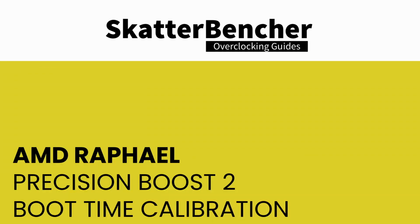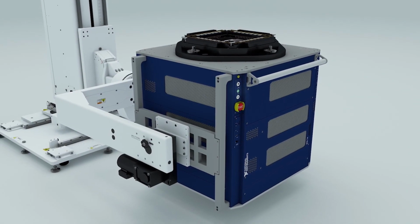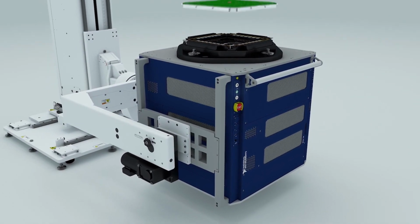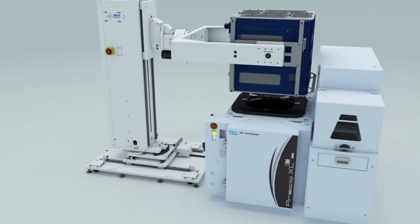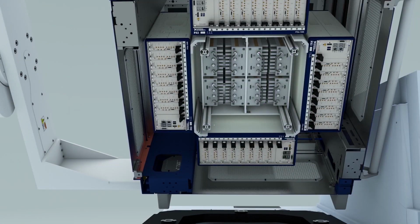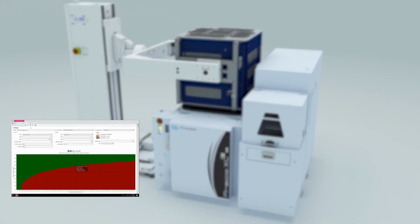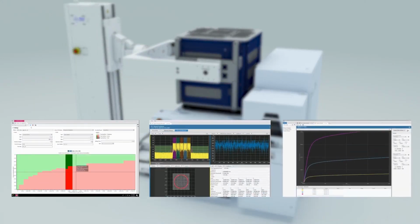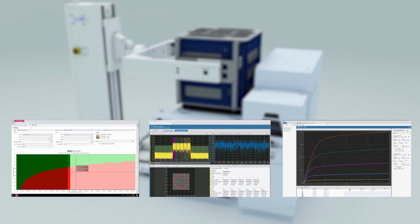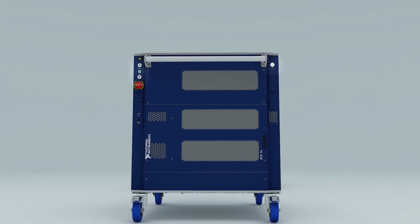And now I hear you asking, what if my power supply is terrible? Great question. AMD uses automated test equipment, ATE, to fuse the VFD table onto a CPU. This test equipment typically provides a more robust, less noisy power supply than a consumer power supply. To compensate for this, AMD uses a tester to platform, T2P, voltage offset. It is often a conservative over-margined value.